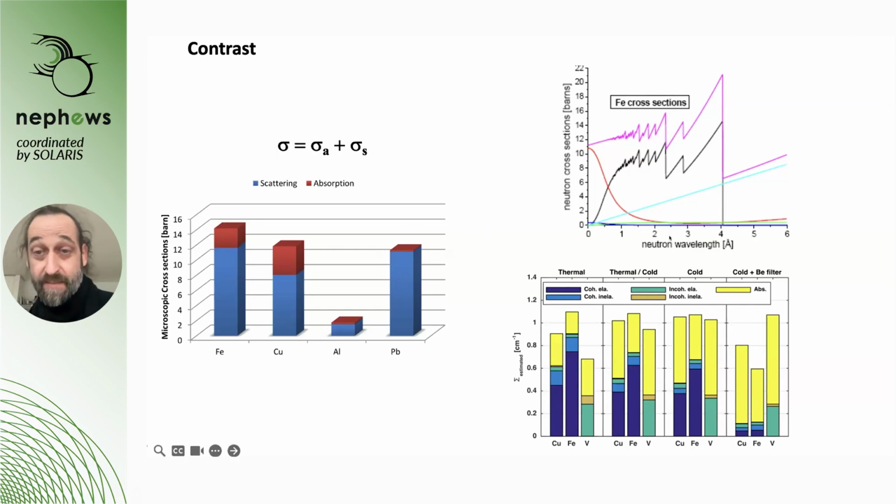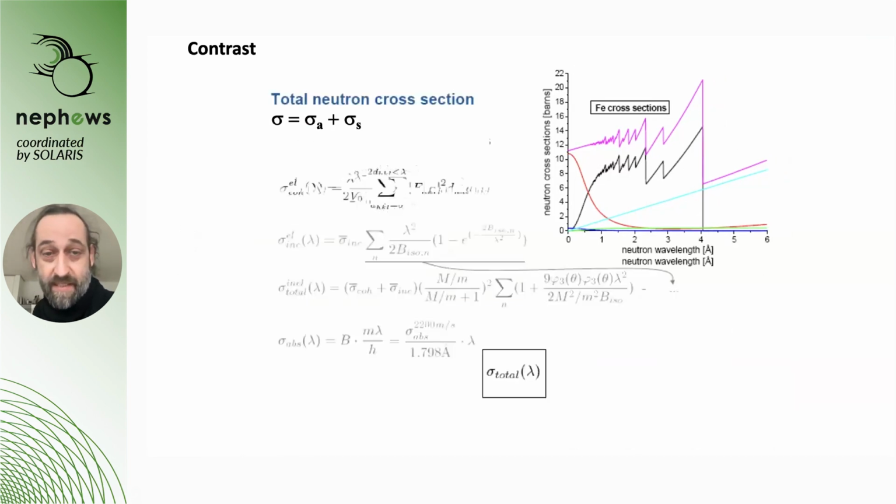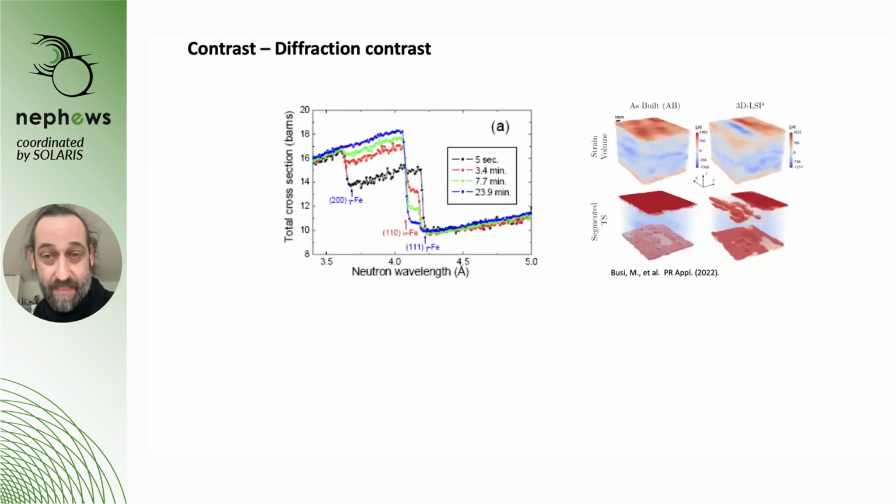But that means now that when you can do imaging with wavelength resolution and you can measure these patterns, then you learn something about the crystalline features of materials. This I mentioned already. So what we can do, for example, when the position of such a Bragg edge, so basically the crystalline lattice distance, varies slightly, then we can see the strain that is on the crystal lattice. So we can map stresses and strains.